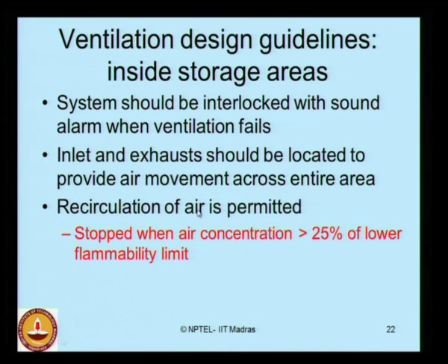The recirculation of air is permitted. For example, if you are using an artificial exhaust or ventilation system, you can recirculate the air, provided it is stopped when the air concentration exceeds 25% of the lower flammability limit of the fuel for which the flammability diagram is available or being discussed. If your air concentration increases beyond 25% of the LFL value of the fuel you are storing, then recirculation should not be continued.